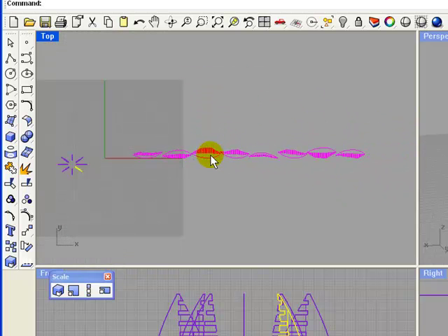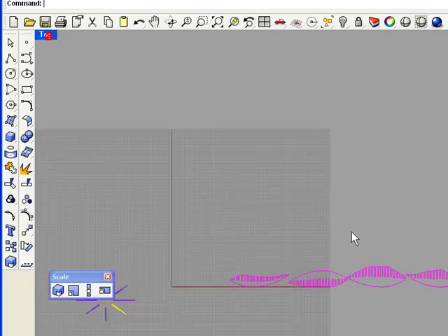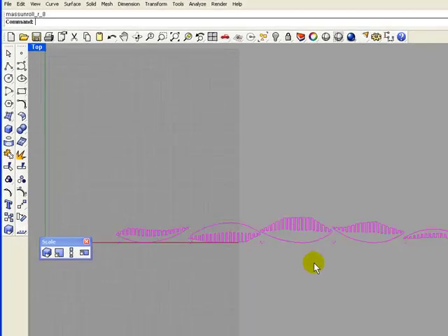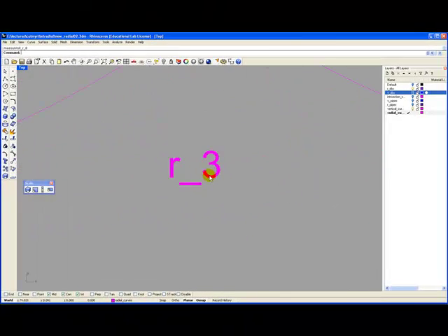Now, let's maximize, let's do some quick cleanup work, and we'll finish off the rest of it. Everything is, right now, magenta, right? As you remember, we want to select all of these. Shift-Control-G to ungroup. Just select our objects on top. Apply our scooch modifier to move them up slightly vertically.